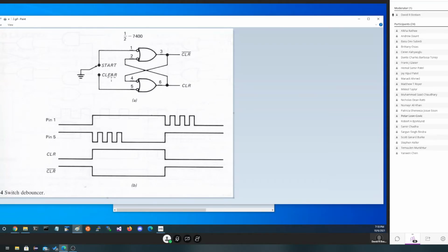Notice we can't push both buttons at the same time because there's only one button. So we've gotten rid of the disallowed state. That means if I leave it pointing at start or I leave it pointing at clear, it'll create that situation and won't change. Because we also can't create the don't change state. Because remember in our truth table, it had two inputs, A and B. Over here, we only have one input. But it can be either this or that.